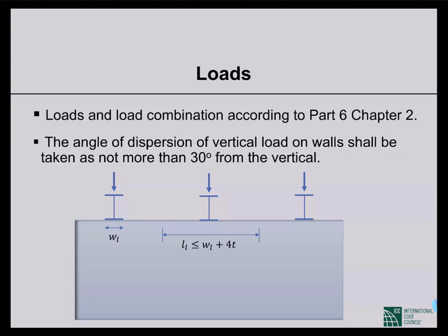But there will be other stresses too. And if we want a loaded length at a depth below the point of contact with the beam, then we can draw a line at 30 degrees from the vertical to calculate the distribution of load.